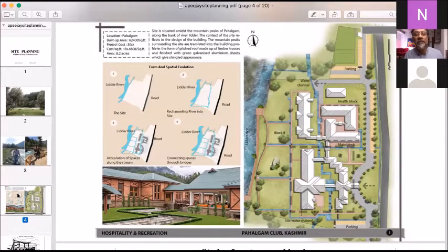Then we looked at materials: why exposed brickwork, locally available, the traditional Kashmiri vocabulary, which uses dajji dewari. In a seismic zone, you see this wooden lattice, the cross wooden latticework that you see on the buildings, which was inspired by the local traditional architecture of that region.